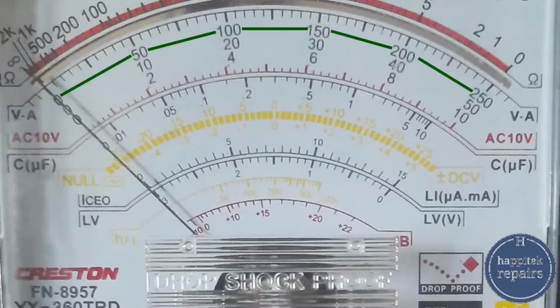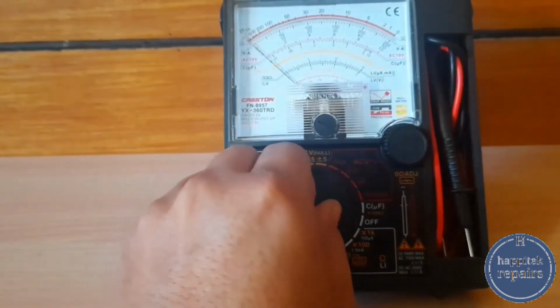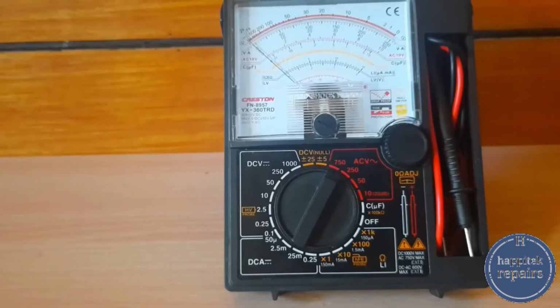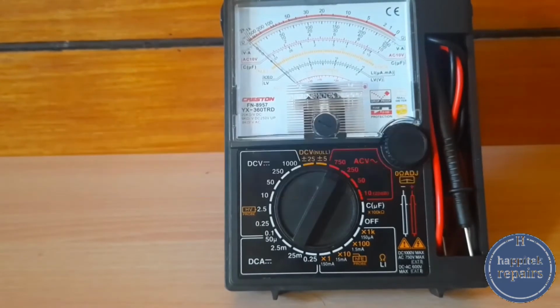What about the 750 AC volt setting? We use 0 to 10, but this time we use a multiplier of 100. Whatever reading we get must be multiplied by 100 to get the AC value. So in a voltmeter, it is a must to learn how to read the voltmeter scale. I will show you the different intervals of every range.